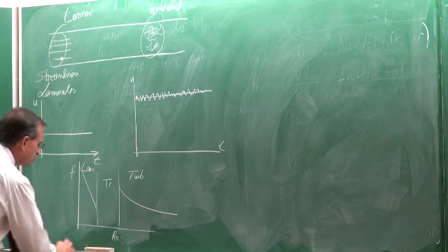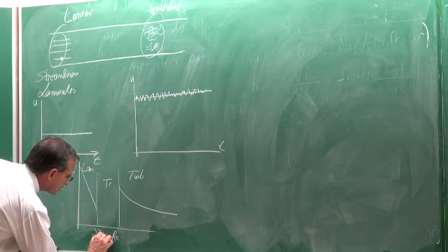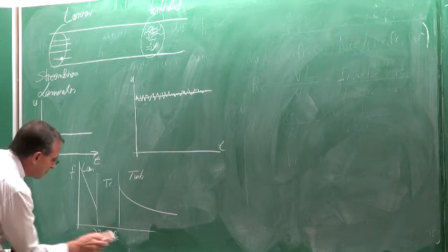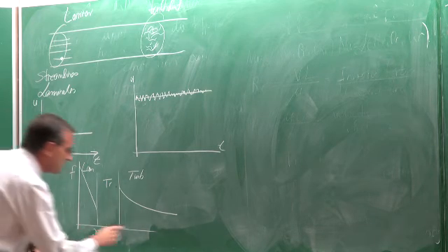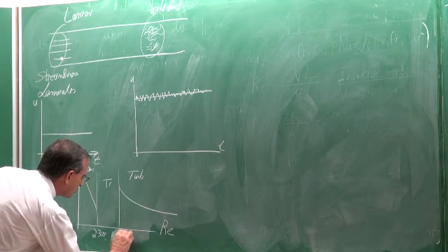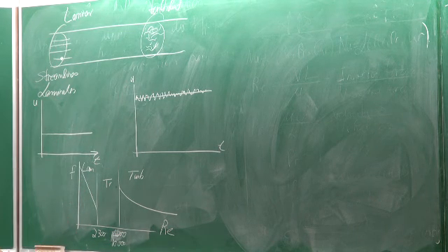And the transition would typically occur at a Reynolds number of approximately 2,300. Okay. Where will the flow again be fully turbulent? Well, it depends on many things, unfortunately, but in the region of approximately 4,000 to 10,000. So if the Reynolds numbers are higher than that, then normally the flow would be turbulent.